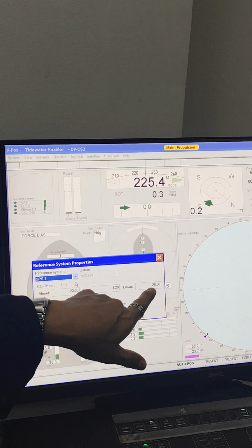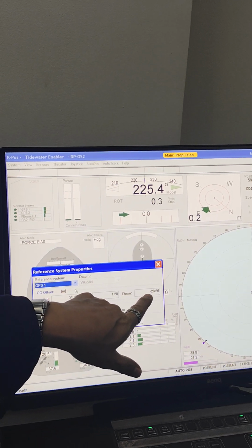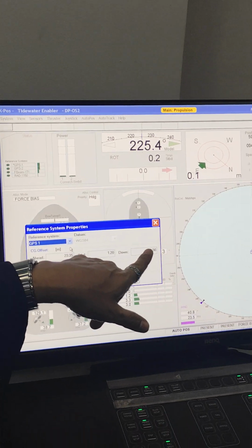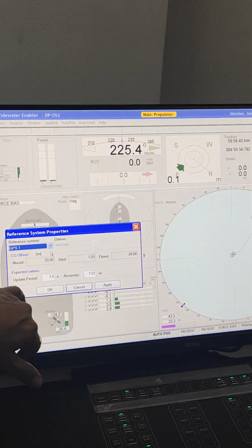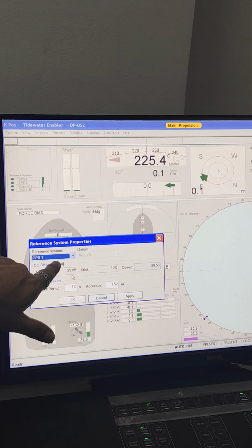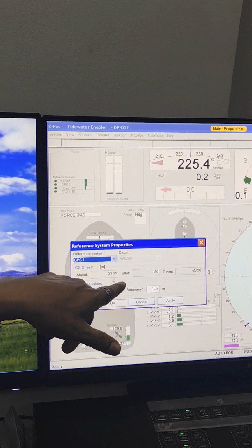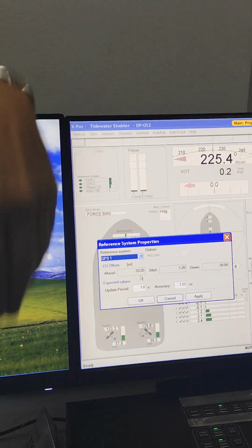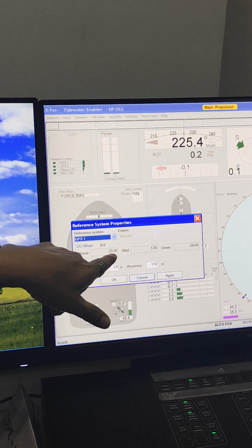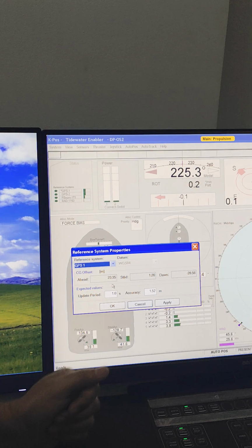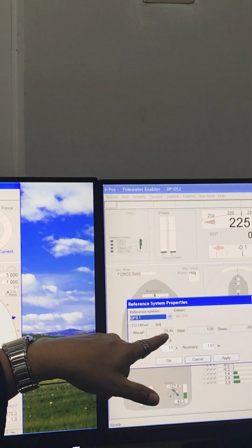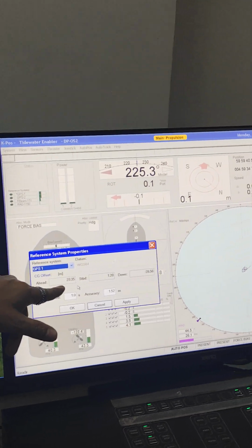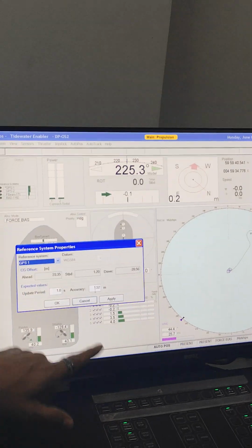And also from the water level, why negative? It should be positive, because forward is positive, down there is negative, so that's wrong. And this one, ahead from the center of gravity, but this is the bridge. That's only should be few meters, no? On the bridge on the Monkey Island, the distance from your drawing, it's about 1.5 something. This is just example. Meaning to say this center of gravity is taken from a conventional vessel, where the bridge is at the aft part. And apply. No, not yet.